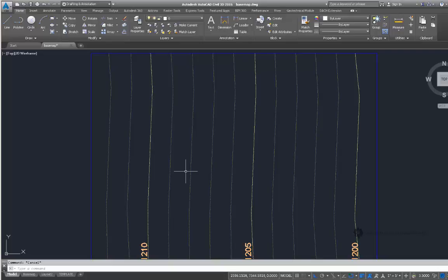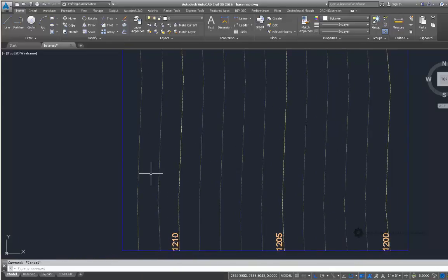So the very first step is we need to determine what the existing slopes are. This is just like when we did it on paper. In order to do that, we need to know what the vertical is, and we're just going to take these two contours here. We know it's going to be a 1 foot vertical change, but we don't know what the horizontal distance is. Well, we kind of know from doing it on paper, but let's pretend for the sake of demonstration that we don't. So I'm going to use this measure tool, and I can click here and click here, and that'll give me a pretty close ballpark.